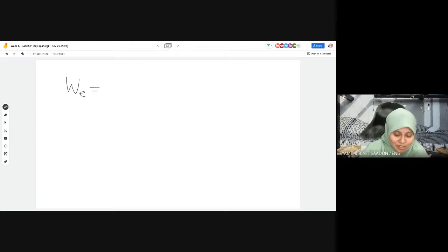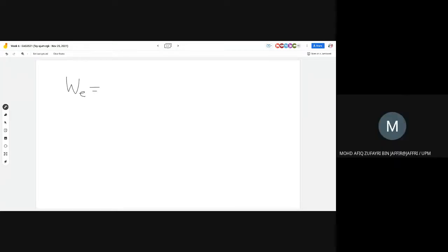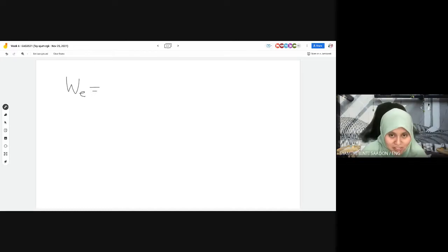Once you get H2, you use the Table A6 that I just sent to you. With Table A6, you have to search using the pressure, which we know. The pressure at this state is 300 kilopascal.